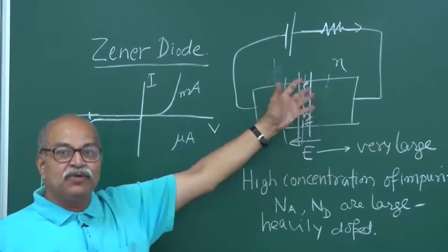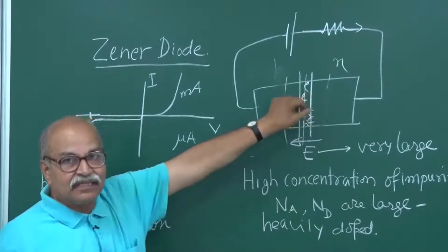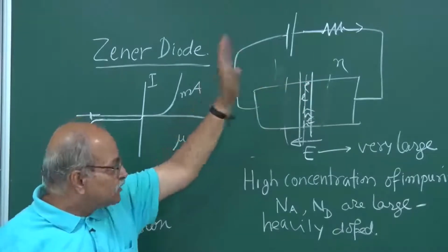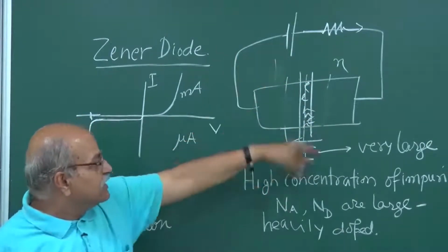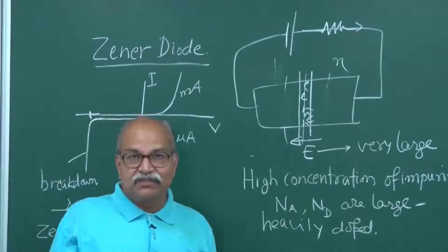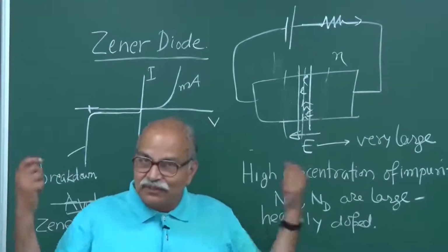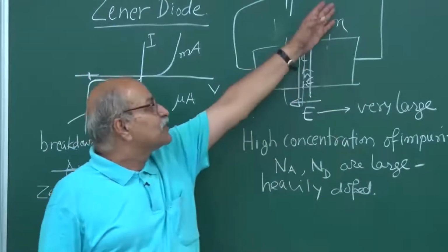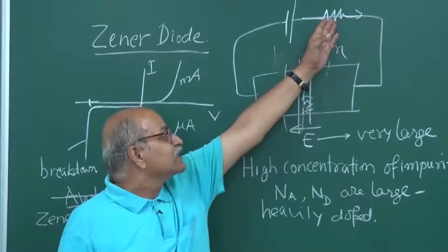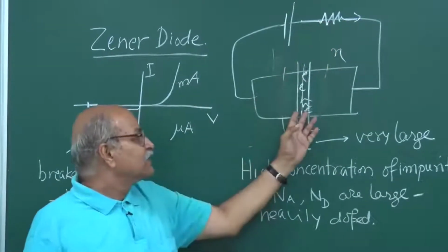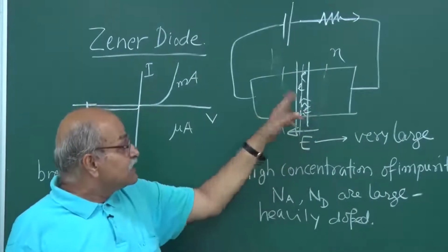The moment it becomes 2 volts, you have all this process starting, and then it cannot increase beyond 2 volts, because at 2 volts itself you try to increase and the current will increase very high, and if you put really more than that 2 volts, then the whole thing can get burnt, right? So you must put a resistor here, so that any extra voltage that drops here and here remains the voltage for which it is created.